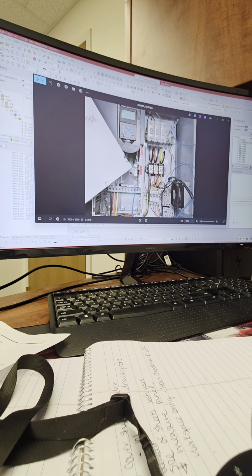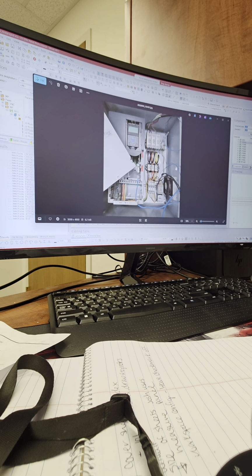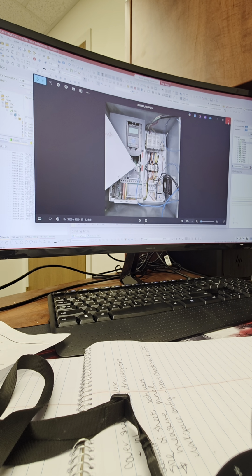Okay. All right, it just gives me a picture of kind of like a couple items that we can place just so you can get the visual to kind of play with it. So technically speaking, we need one DIN rail on top and one DIN rail on the bottom. Considering the middle portion there looks like a plate mounted distribution block. Yep. As in does not need a rail, right?